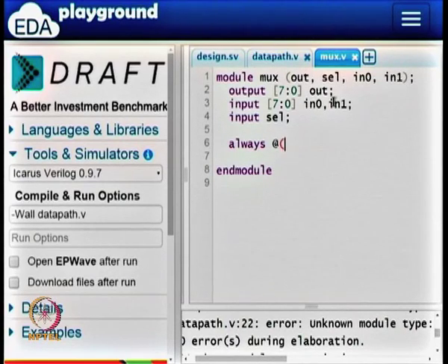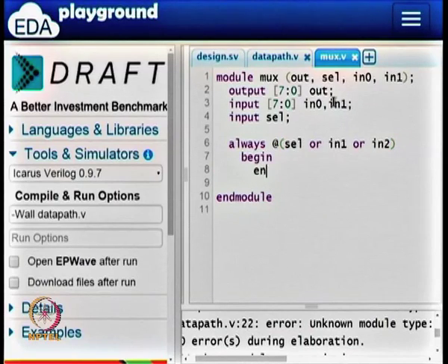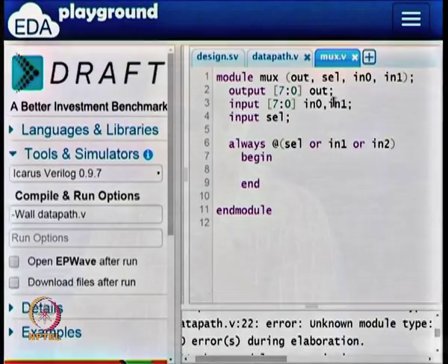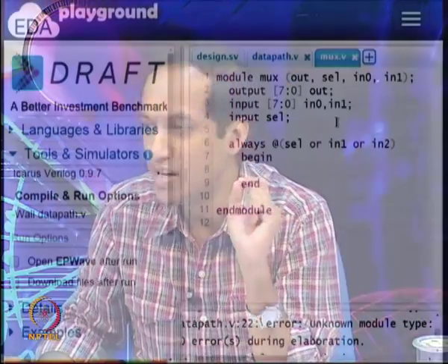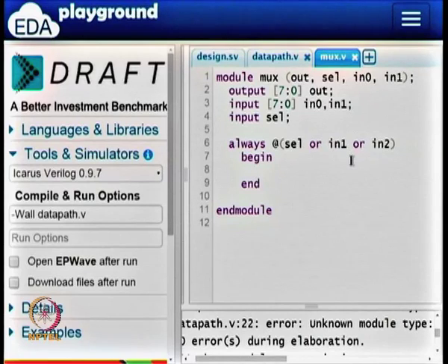I am going to use the familiar always block. So always at select or in 0 or in 1. What this is going to do is, if either the select changes or input 0 changes or input 1 changes, this is a combinational circuit, so the output is supposed to change, right. The interesting thing is that in 0 and in 1 are now 8-bit values, and if any of the bits in input 0 or input 1 changes...